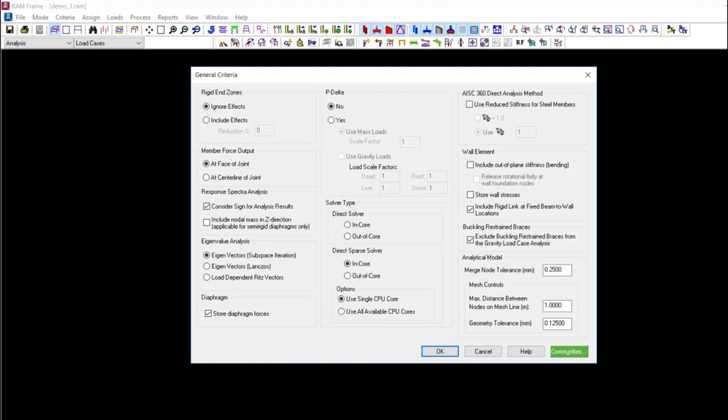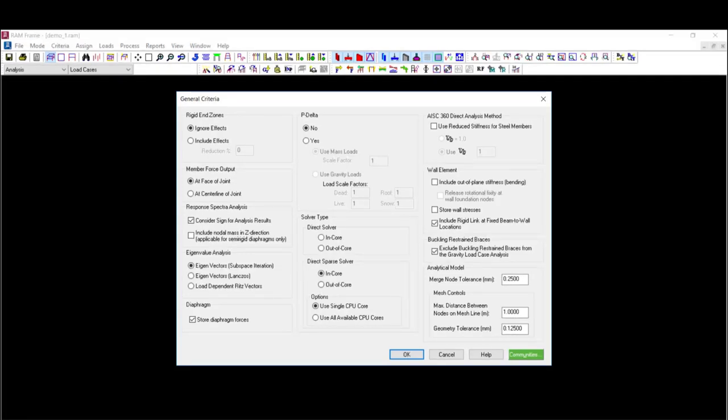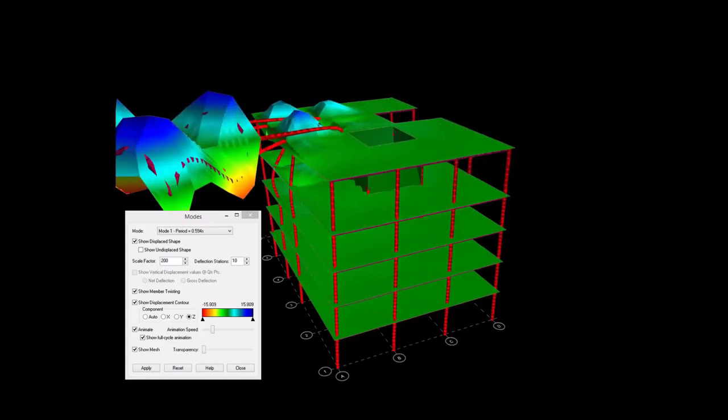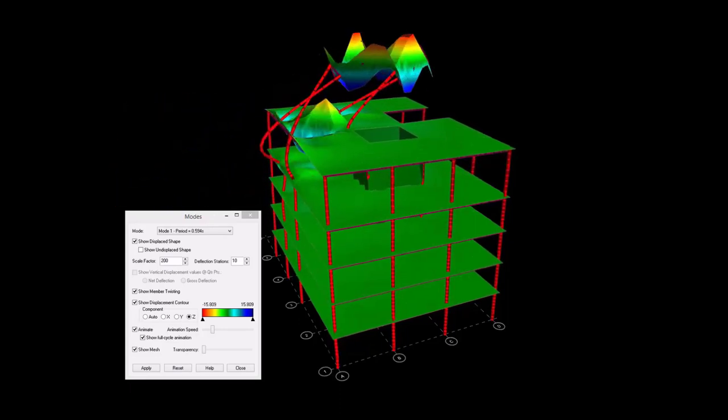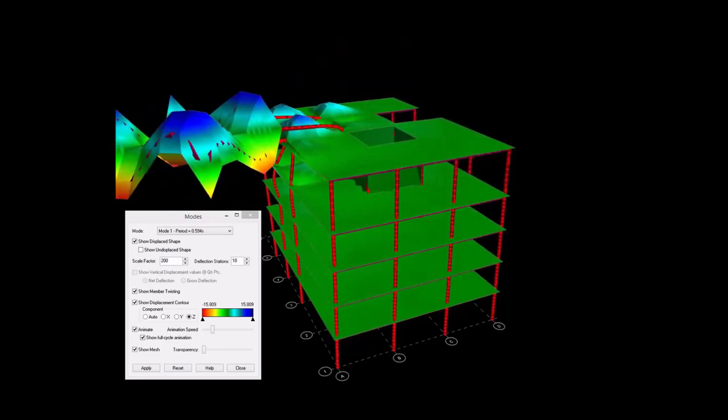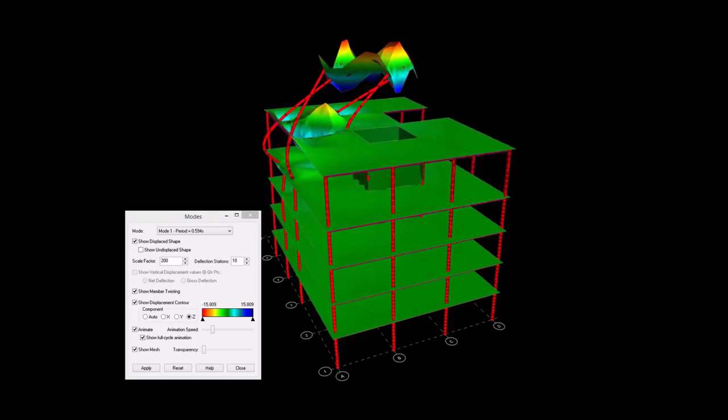Third one is the Ritz analysis. This is a very interesting part of these eigensolution methods. Now let's take an example as shown here. Imagine if you have a mezzanine floor or a steel deck or an antenna model in the structure whose stiffness is insignificant in comparison to the main structure.